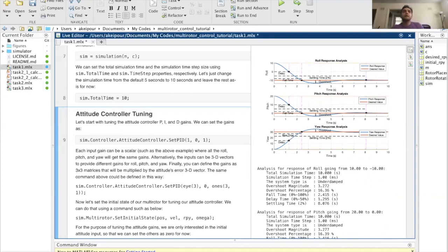Even more important than achieving the best time is for you to actually learn how to achieve that. I have written it there. I'm not sure if it's clear. You can start with P. Keep the D at 1. Increase the P until you see a weird response. Then increase the D a bit. Again, go high on P as much as you can, as much as it actually changes the result.